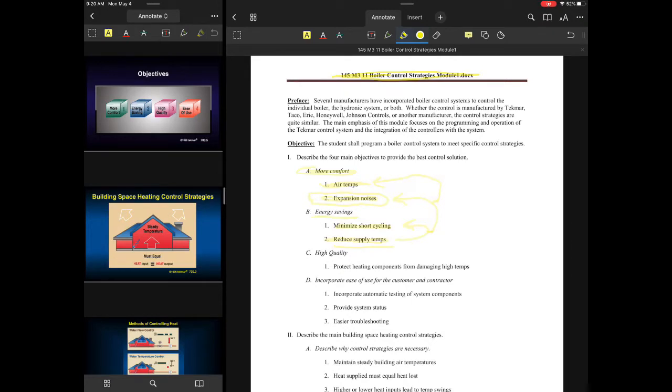And if I can reduce that, I can essentially take care of all of these things, so this is definitely related. Now, on certain applications, when you do reduce supply temps, it's way more advantageous if you can have a modulating boiler system. But there are limitations within that.